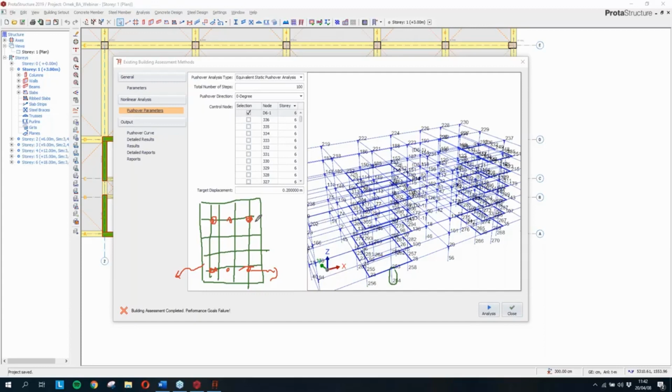After preparing those fiber section definitions, the nonlinear section definitions, we prepare our force deformation. We export our force deformation relationships as moment curvature relationships.